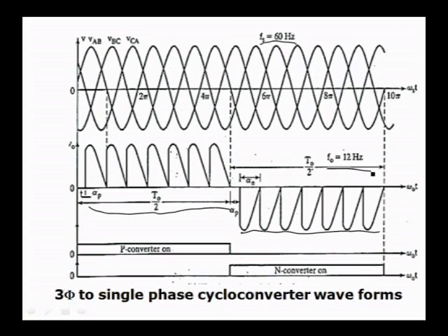So in step up, I stressed that the thyristors are forcefully commutated, by forced commutation, already studied in detail in previous sessions. So here they are line commutated, naturally commutated. That is the difference, and that is another advantage of step down converters. We don't need complex circuitry for commutating thyristors. Forced commutation is not required in step down cycloconverters.